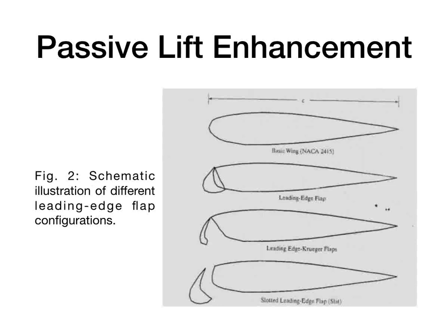One solution for leading edge separation is to increase the leading edge radius. This is the principal effect of a leading edge flap, which generally consists of a hinged portion of the leading edge, which deflects downward to effectively increase the leading edge curvature. A variation on this is a Kruger flap, which consists of a hinged flap on the lower side of the wing leading edge, which extends out into the flow. This approach is lighter in weight and as a result popular on large aircraft with large wingspans.